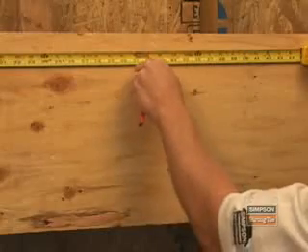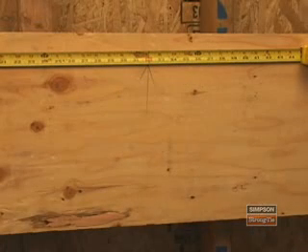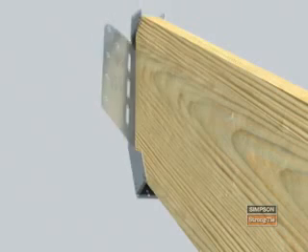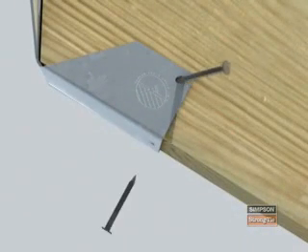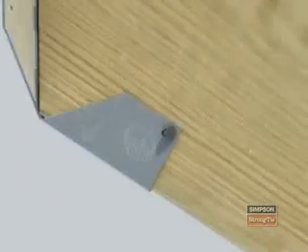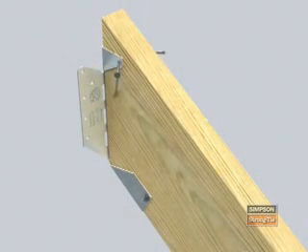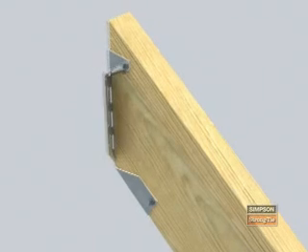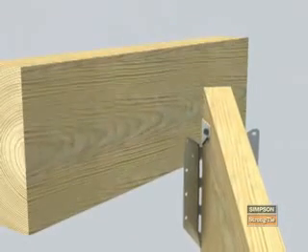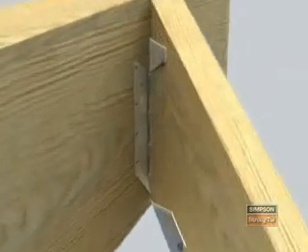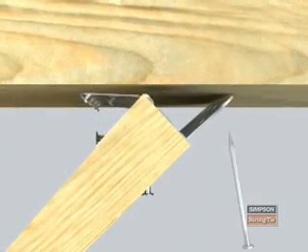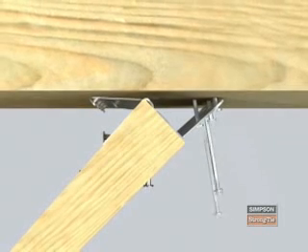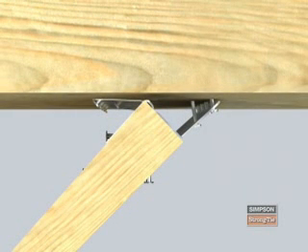After finishing any necessary preparations, mark the joist or rafter location on the ridge beam or header. Then attach the hanger to the sloped or skewed end of the joist by first installing the seat nails, which are 10 by 1.5" short joist hanger nails. Bend one flange to form the acute or inside angle desired, and position the hanger and rafter assembly on the header. Using 10 common nails, fill the oblong holes by hammering parallel to the joist. Using your hammer, bend the other flange back until it touches the ridge beam or header. Fill all oblong holes with 10 common nails.